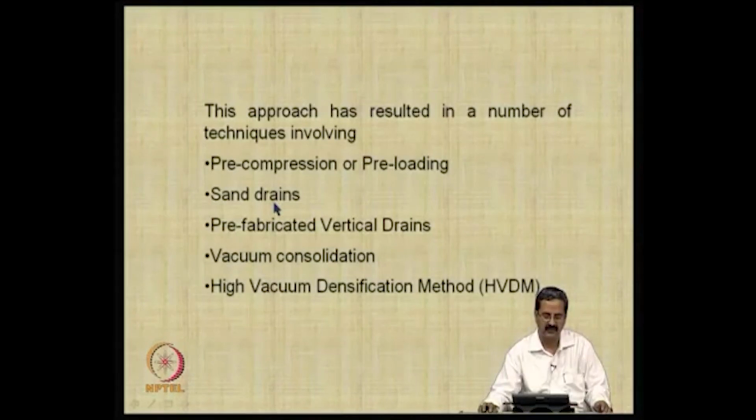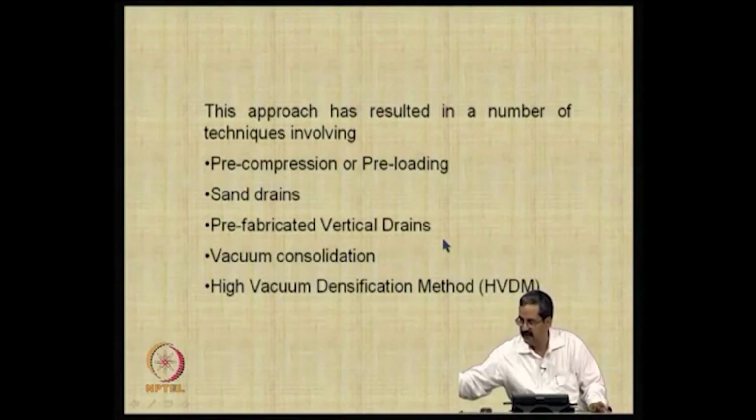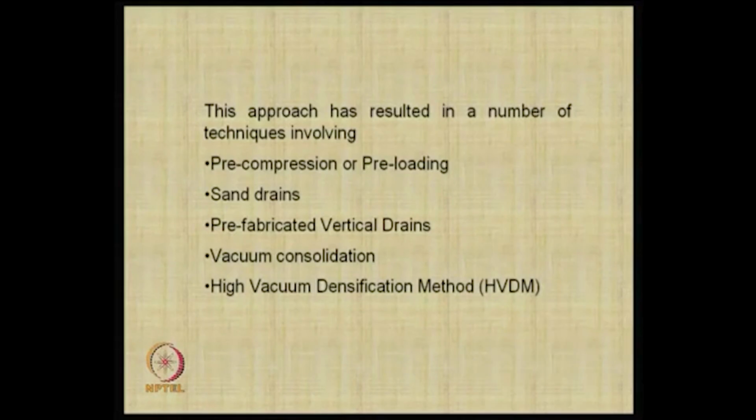Sand drains were what people were using in the olden days, but now you have what are called prefabricated vertical drains. You can see prefabricated vertical drains, in which, if you put it in the soil, this is called geotextile, and inside you have a drain which has drainage channels.